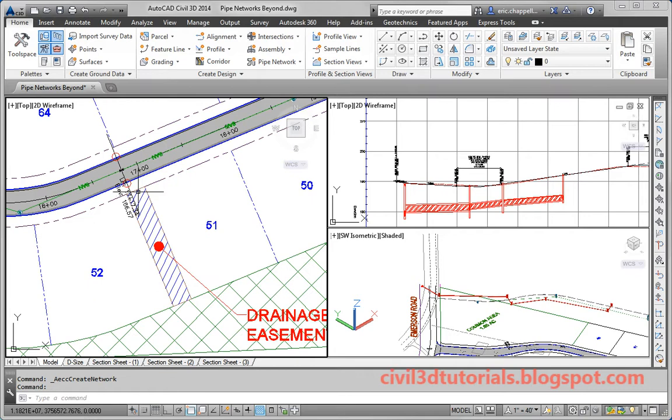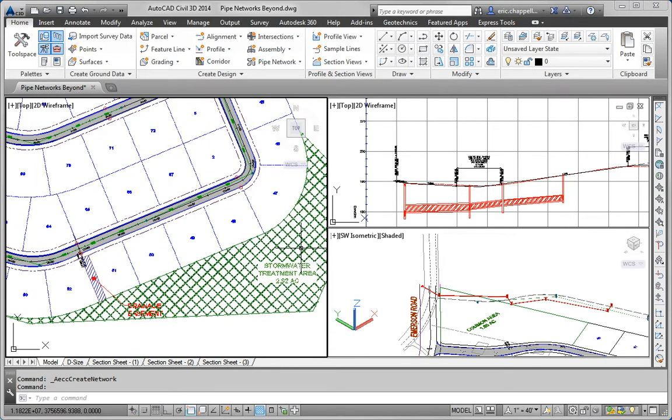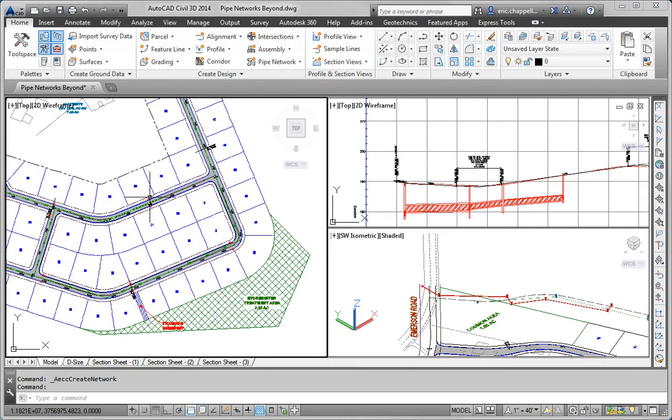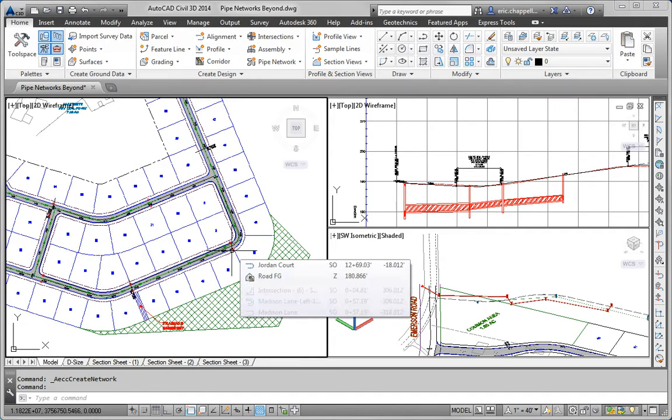We're going to exit the system with a 36-inch pipe and an end wall that dumps into this area, so we're looking at maybe placing a pond in here. The pipe should go from 15-inch in diameter to the 36-inch pipe that I just mentioned. So the pipes furthest upstream, for example here and here, should be 15 inches, and they'll get larger as we go downstream. Now we're going to kind of arbitrarily pick where they change size, but really you would do some hydraulic calculations to figure that out and size the pipes based on engineering principles.